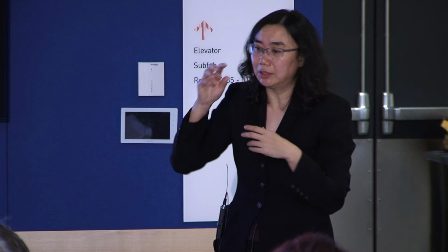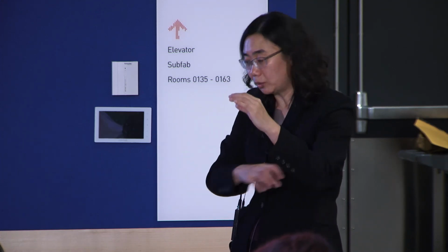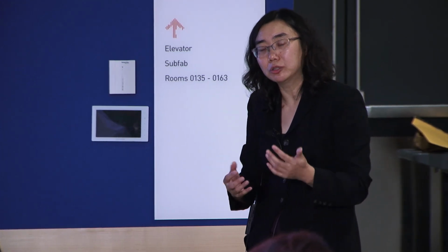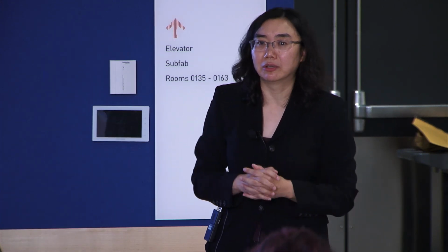The big advantage is now you can imagine your read and your write are separated. So you use the current underneath in the wire to write your free layer, and you use the magnetic tunnel junction to read it, right? One of the things I showed earlier is the operating window: the write voltage and the breakdown voltage have to be further apart. If you can separate the read and the write, then there's a huge advantage, because when you read, you use a very small voltage. You don't really worry about breakdown. The write, you use a different path. But in terms of efficiency, people haven't really shown any advantage for this SOT device.